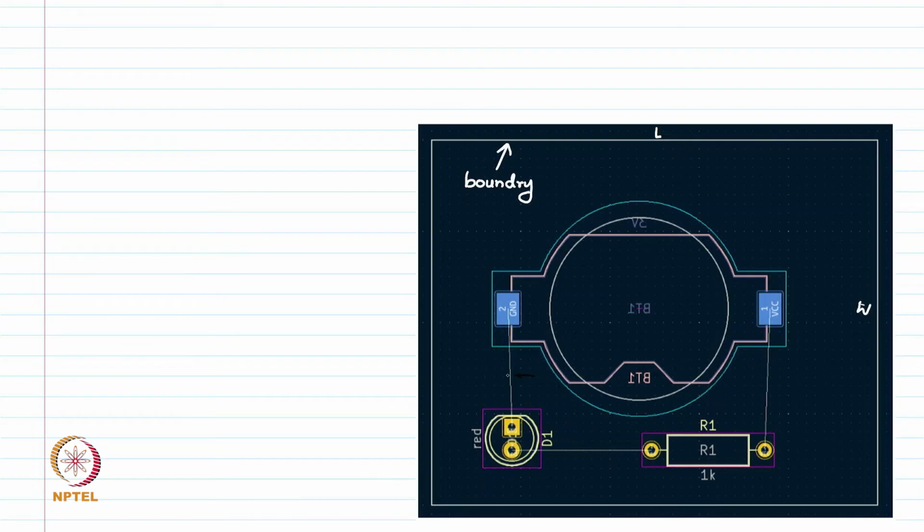So for example, we do not want so many rat nests crossing each other, because later on we need to replace these rat nests using copper wires, and if they are overlapping each other, we need to put a via to bring one to the other layer, otherwise two wires will get shorted together.